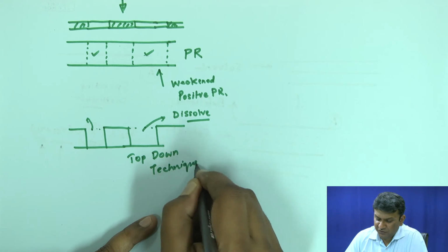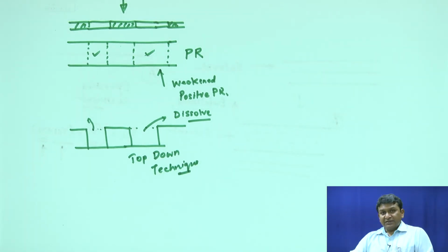Pretty similar is also the approach for some of the soft lithography methods, but honestly speaking, if you are very critical about soft lithography techniques, not all of them are top down techniques directly, but generically soft lithography methods or any patterning techniques are considered to be top down methods. For example, if you remember micro transfer printing, which is the only method that is capable of creating 3D structures, it is actually a bottom up technique, because you build layer by layer. One layer you first deposit on your substrate, then you add more layers. So it is all there.